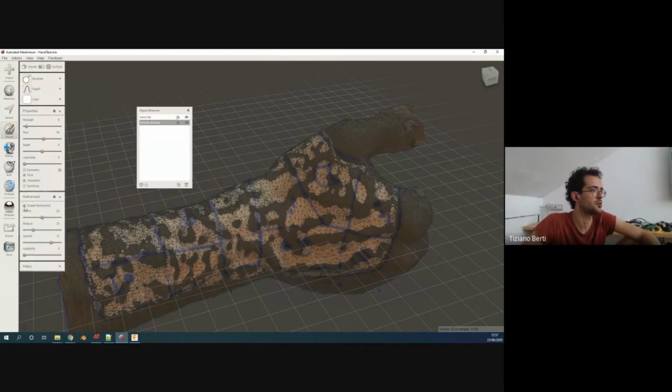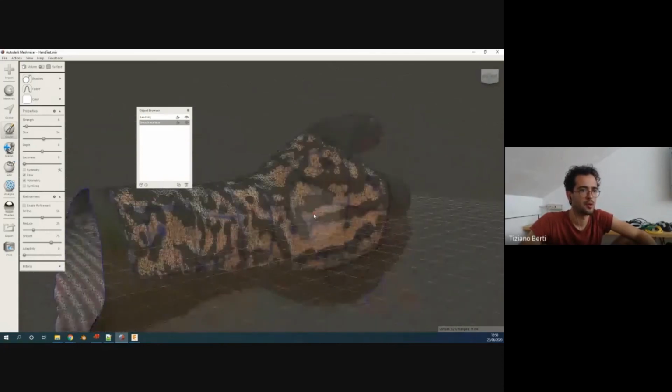You can choose to not enable refinement because this will change the mesh as you sculpt, adding or removing polygons. And the other thing is, I think with Control, we are pushing inside, and with the normal click we are pulling out. So with this tool, I can correct the mesh where I feel I'm going too close to my hand.